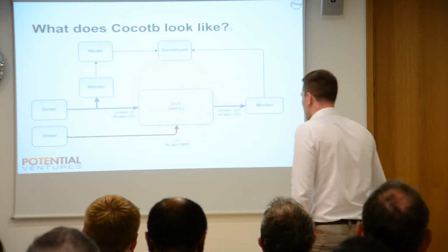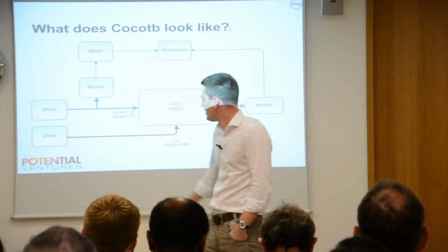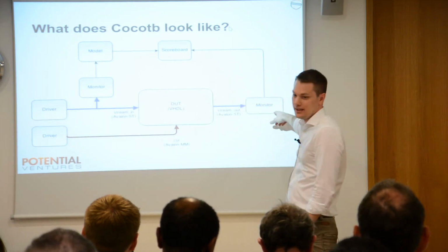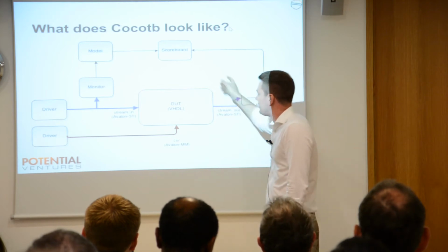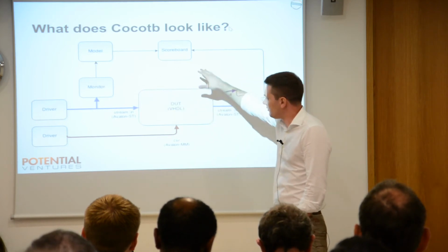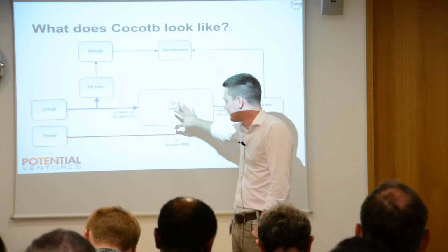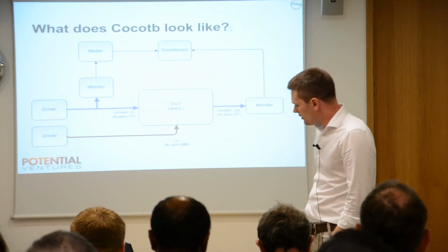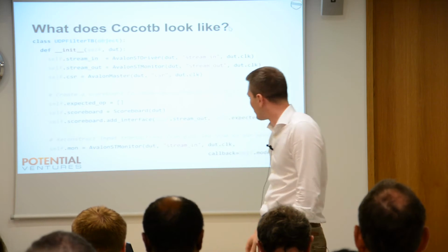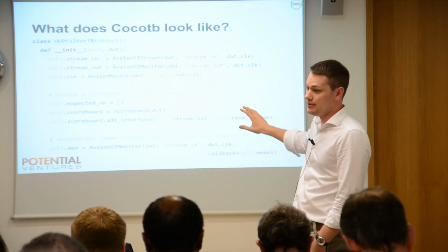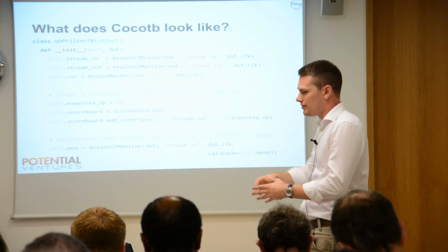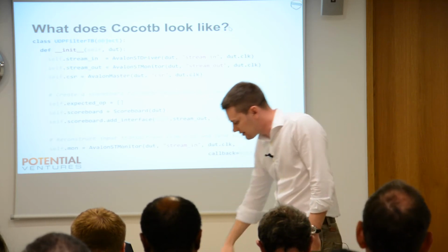So this is the structure we've just created with those lines. We've got something that sends transactions into our device under test, and something that takes the transactions that come out. We compare them going through a model on the scoreboard. We also have something to set up configuration status registers. And I don't think you could describe that in a more concise form than this code. So that's basically what we've aimed for. You don't have to instantiate anything around your design. It's concise, it's quick.